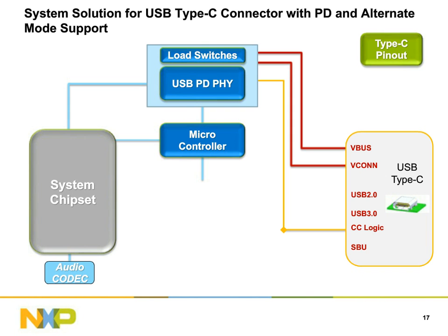And if you are making a design or a device which necessarily does not support that high a voltage or current, you want to put a load switch in your design so that by mistake, because of a faulty source or because of whatever kind of error in the connection, if your design is 5 volt and your device sees higher than 5 volts on its bus, then you want to make sure that your device is not damaged, your design is not damaged, and that's where a use of load switch will kick in.